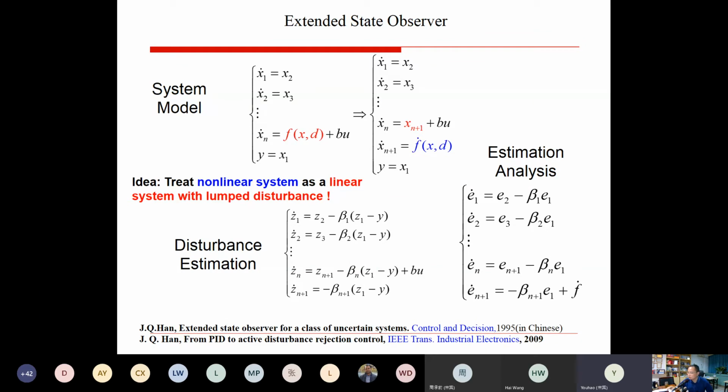And I have another question, also about ADRC. To the best of my knowledge, the condition for f dot is that it is upper bounded, but you mentioned that f dot needs to converge to a constant. Rigorously speaking, it is not bounded. Consider an example. If f of x is x to the power of 3, then f dot will be x squared. It will not converge to any constant, and it is not bounded, because it will increase with the state, right?